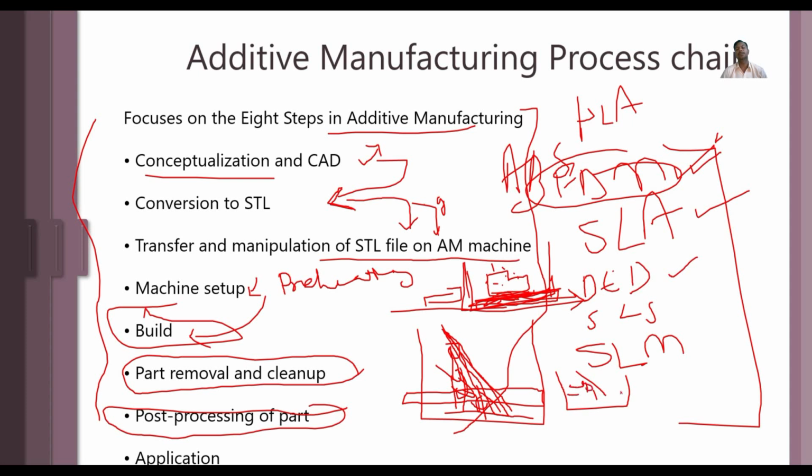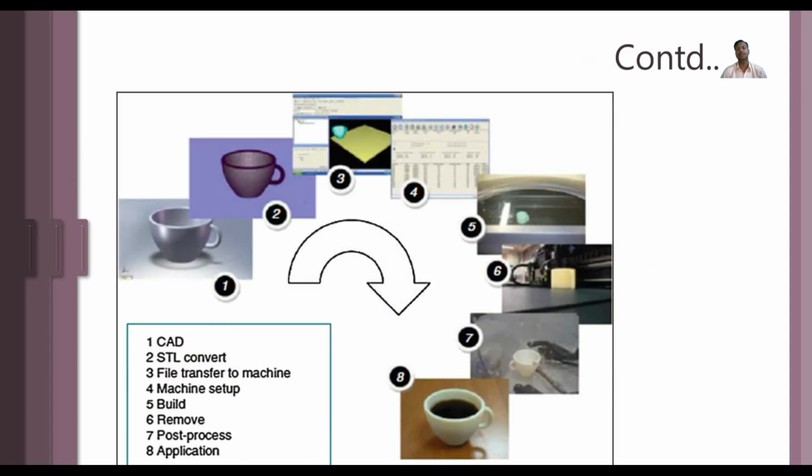Simply we dip it into some alcohol based liquid so that the supports can be easily removed and we can achieve a smooth surface of objects, especially for applications like jewelry and surgical operation sub parts, where the surface finish is very much required. Intricate shapes with lesser volume objects can be printed in SLA machines. Later, post processing can be used based upon the application.